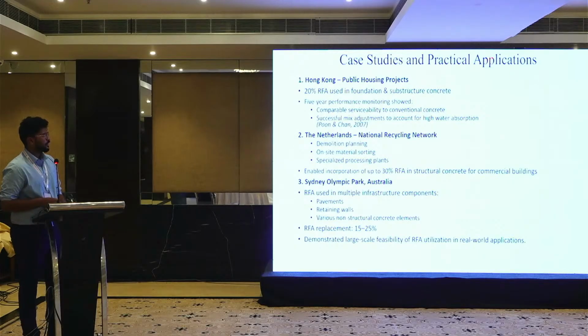We have also looked at case studies. They have used 20% RFA in foundation and substructure concrete, and in the Netherlands, demolition planning enabled 30% RFA in structural concrete, and in Sydney Olympic Park, Australia, pavements used RFA replacement of 15 to 20%.